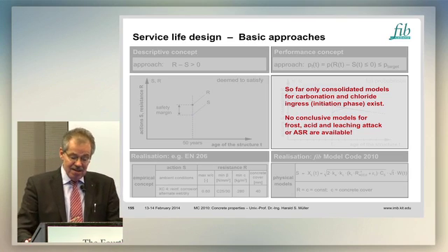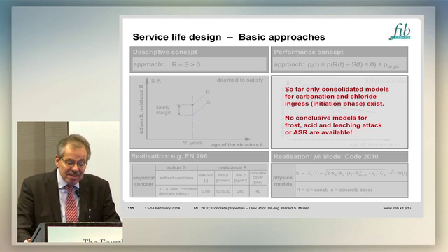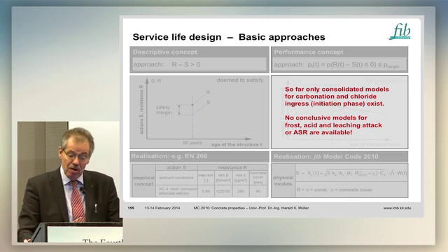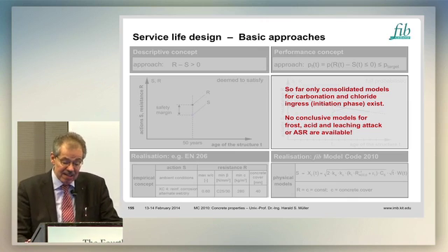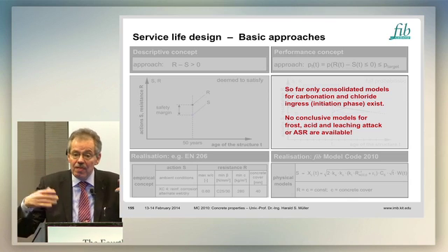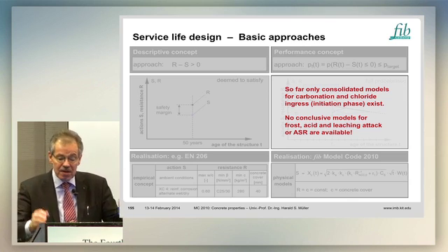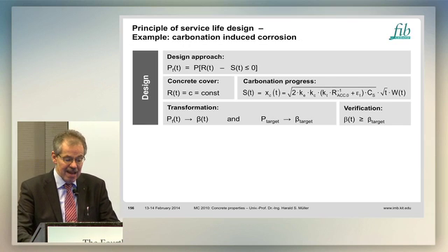I have to admit that so far we have only consolidated models for carbonation and chloride ingress in the initiation phase. We have no conclusive models. We have some ideas about frost, acid, and bleaching attack and alkali corrosion, but they have not been developed so far that they could be included in Model Code 2010.